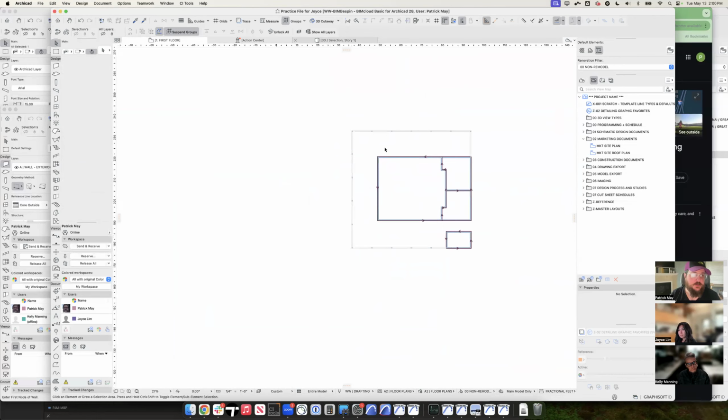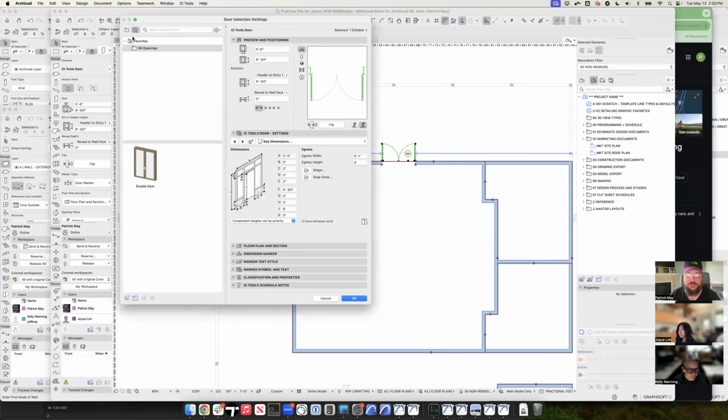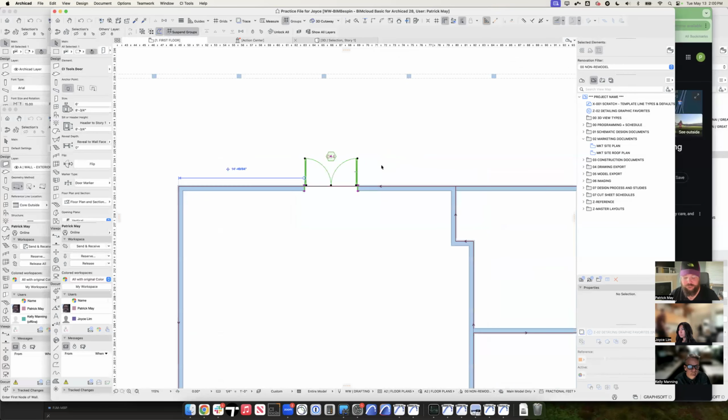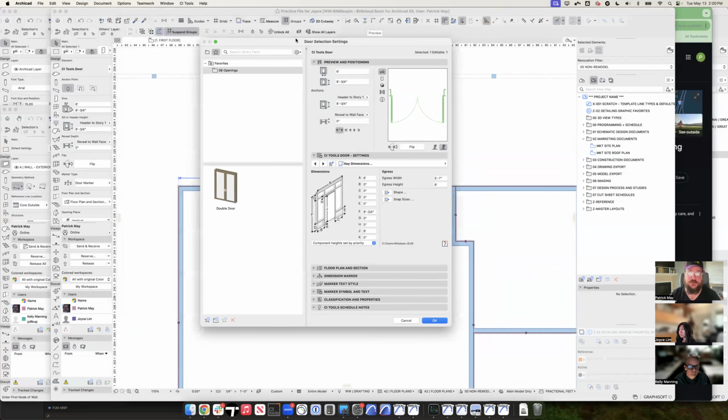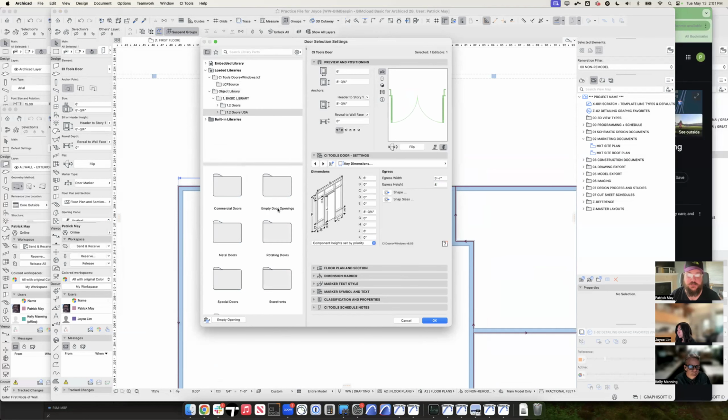Okay. Let's take a look at the door tool. I'm going to actually model the big surface sliding door here as an example. So if I just drop a door in here, this door is set from the favorites here, and that star. So just setting it here means that I don't have to worry about what the marker type is, what the pens are. It's the correct door. It just doesn't have the correct operation. So for the door tool, if we look here, there are the CI CAD image doors. There's also everything in the ArchiCAD doors.